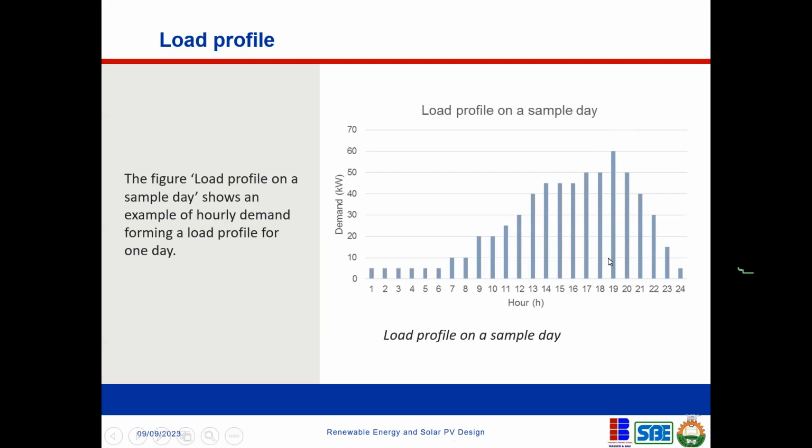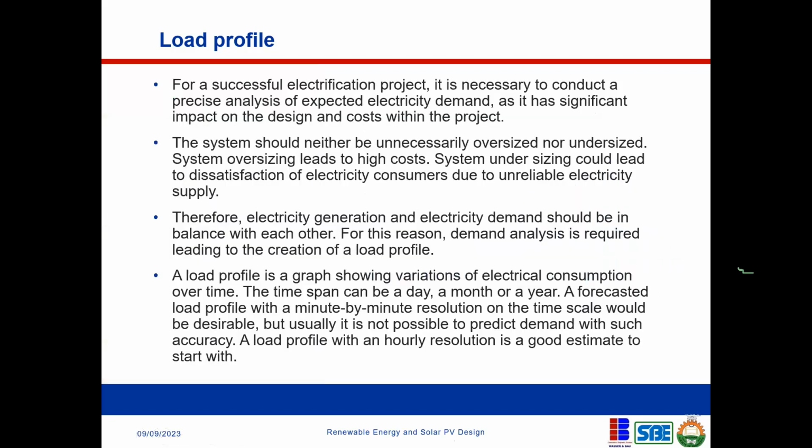Now the question, when you have this kind of peak profile, you may want to investigate what is the reason why you have it. It is possible that if the pumping machine is what is causing this, for example, you could actually say, okay, not on the pumping machine this time, turn it on anytime here. So you can reduce your capex, your capital investment in your solar project. So the system should not be unnecessarily oversized or undersized when you're designing your systems for solar PV.